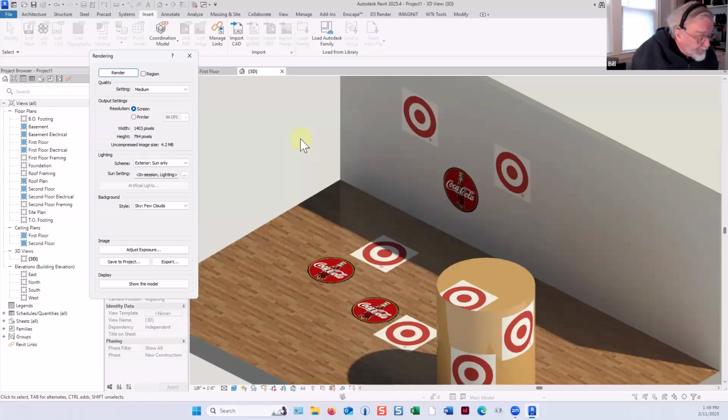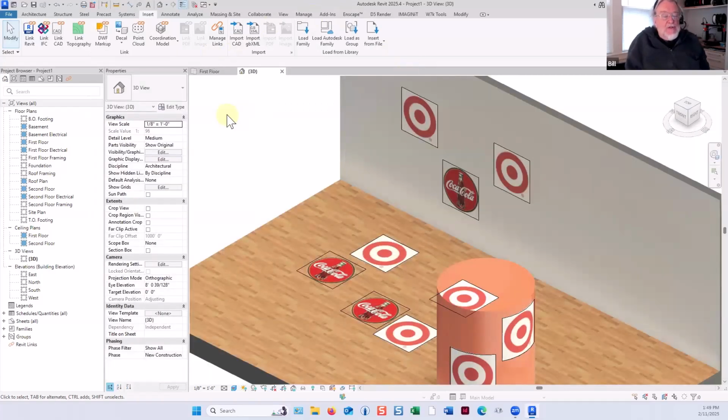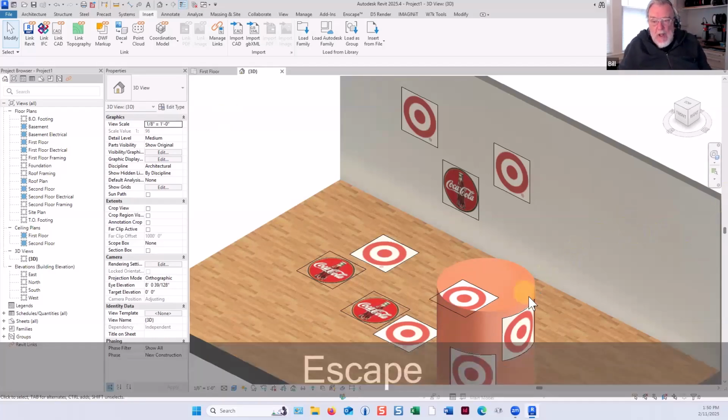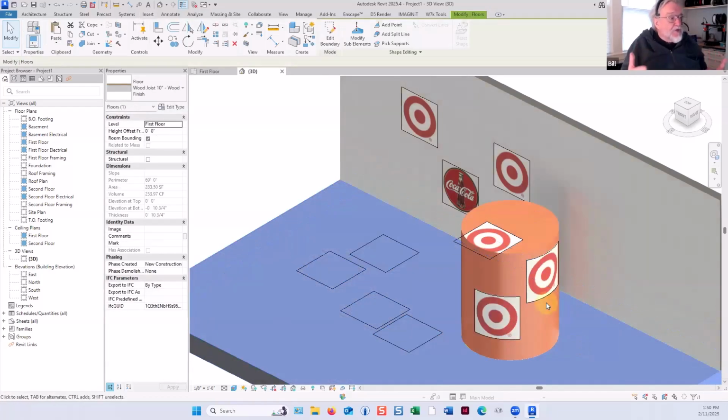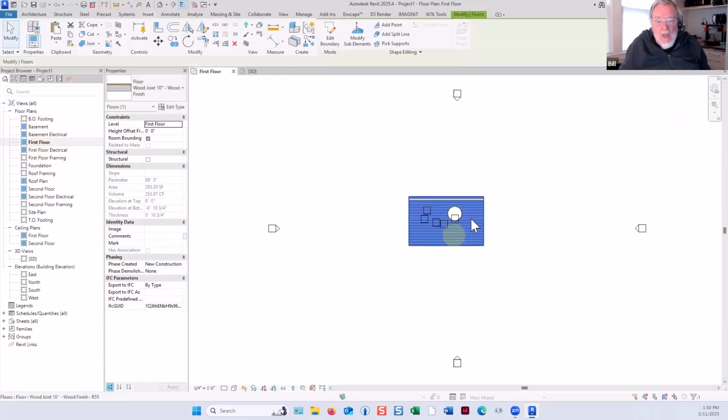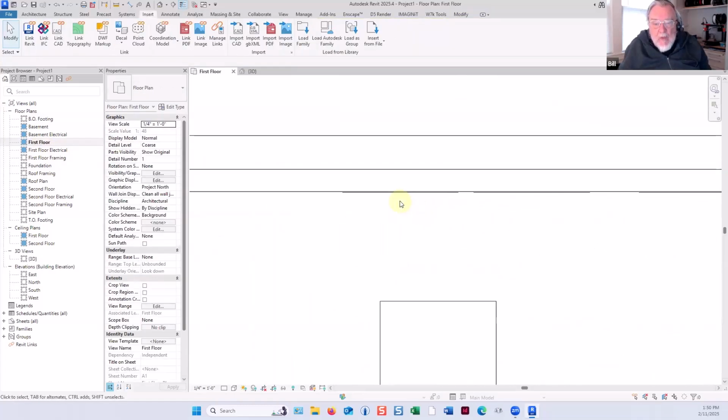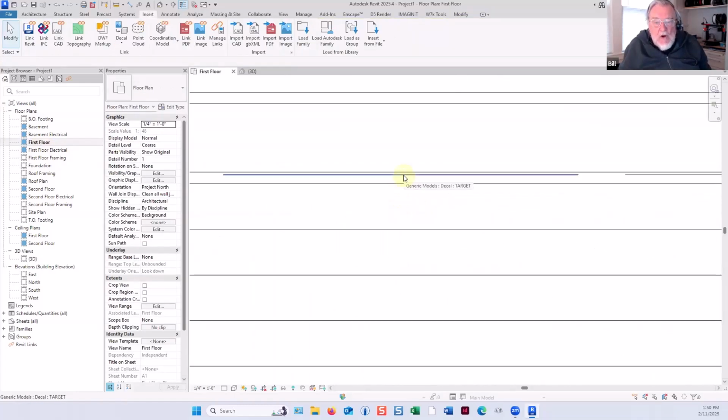So over on page 4, let's make a family picture frame that we can apply that to the wall and then stick an image into it. Oh, and one thing, just to make it clear, when I move the object, the decals go with it. They're not like in space somewhere. They're actually attached to it. And in fact, let me go into a plan view. If we zoom in on this wall, we can see that what the decals are is like an image that's floating like 1/8 of an inch in front of the wall, just so you know what those are when they start showing up. But they do have their own sort of separate existence.